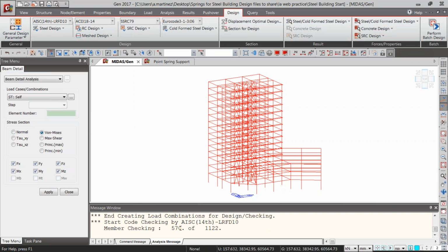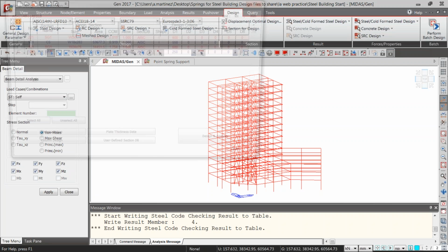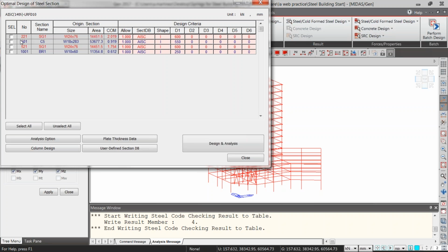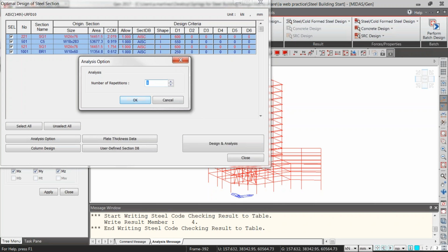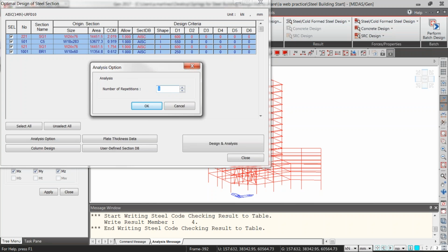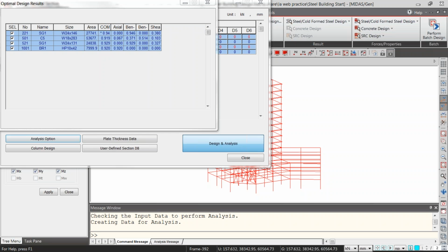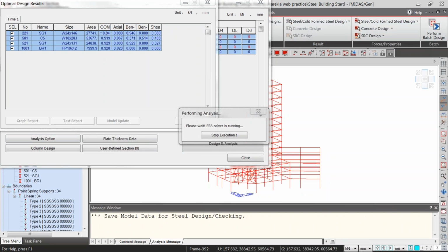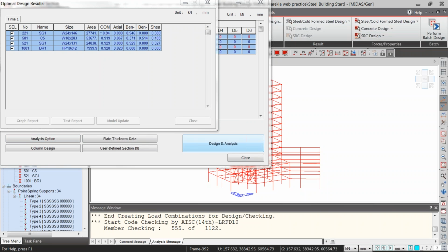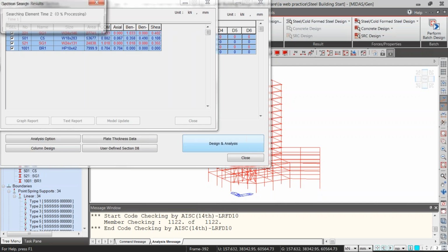And we see it here going through all the steel members. First we see the same thing that we saw on the check, that two of the sections don't pass and two do. So we can just select everything and tell the program to design it. We can even give it information about iteration processes. The program sometimes needs to go through several iterations. If, for instance, it changes two of the sections, it has to recalculate the new distribution, and that might affect the third section. So even if there are no changes, the program will let you know that after the second iteration there's no need to go through a third. You can be more sure than just running one iteration manually. You can just tell the program to go ahead and run two or three, however many iterations, in the process.